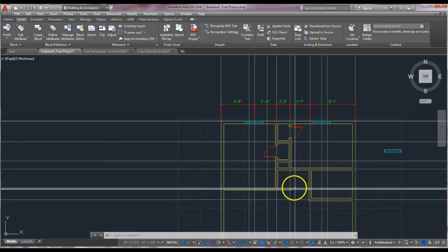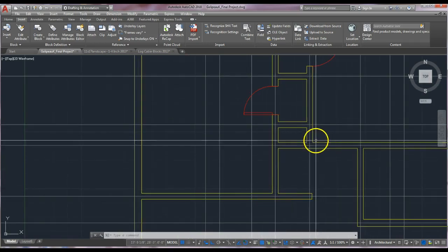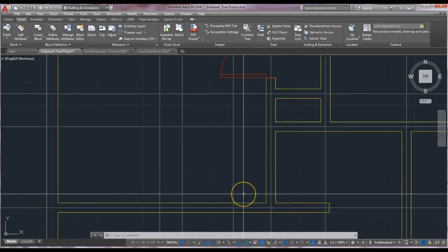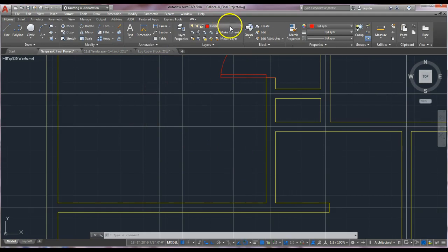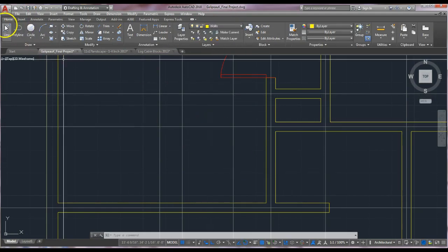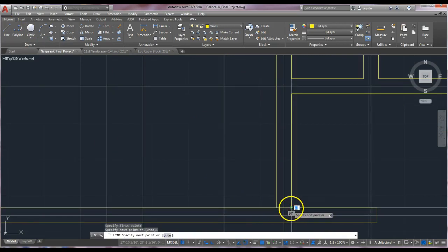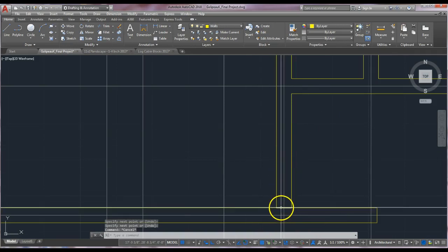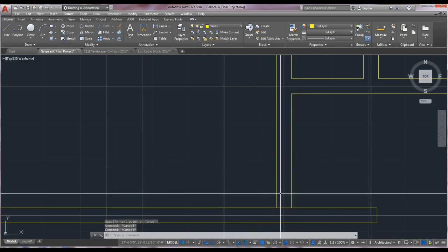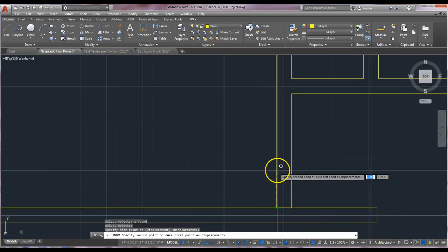So the bedroom doors have a 4-inch trim area before the door starts, here and here. So what we can do in this case is to first go to the wall layer and then choose the line command. And I'm going to just draw a line right here, and then I'll be moving and copying that line. So this line will move in 4 inches. So move, select the line, base point, drag your cursor up, type in 4, enter.